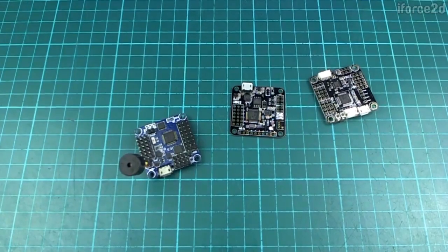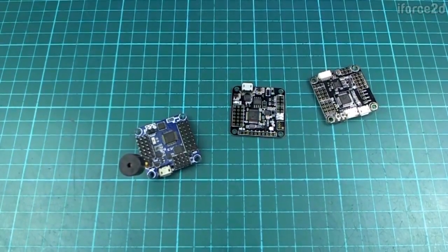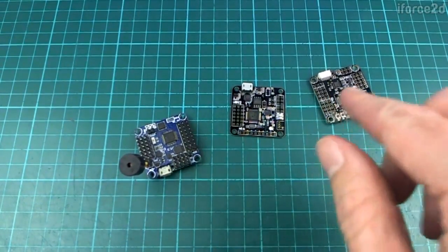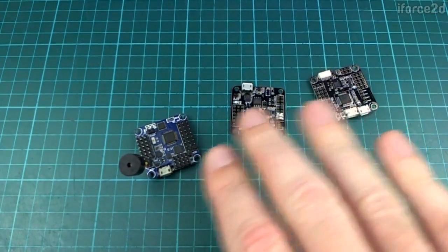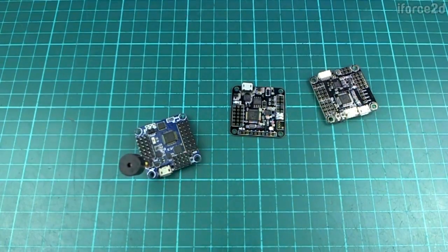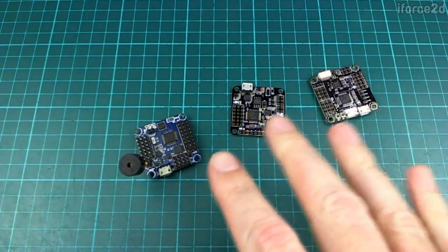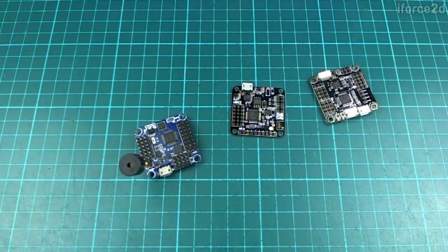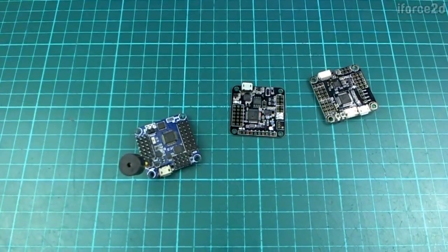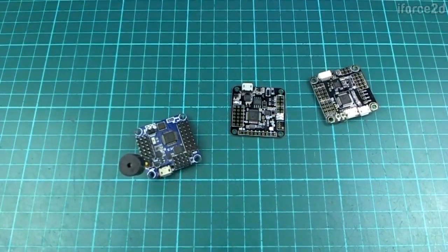So as we know, a flight controller is a little computer, and I have three examples here that I'll take a look at during the course of this video. And these are pretty typical things that are in use these days. And they are a 32-bit CPU running at about 72 megahertz for the lower end ones. But things are changing very, very quickly, and the 72 megahertz CPUs are already starting to look a little bit slow.